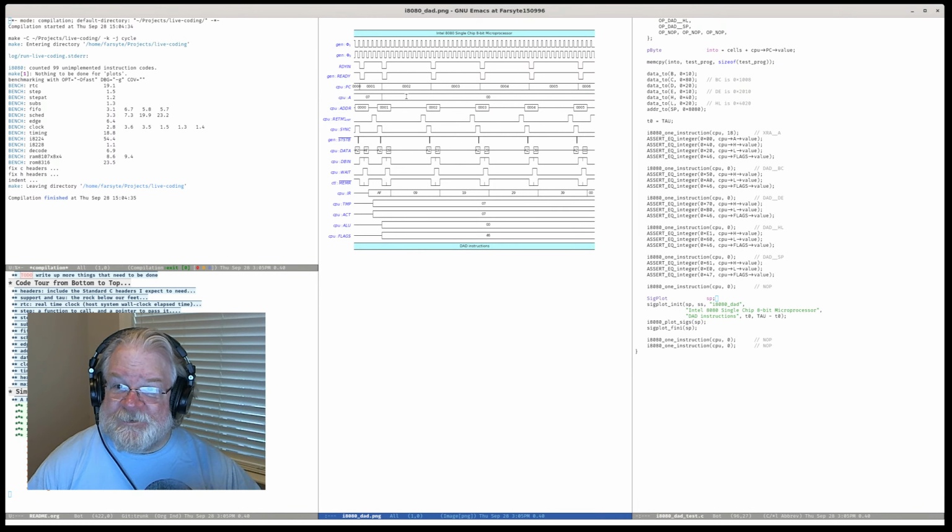SP is marching across. The accumulator gets cleared to 0. Here's our ret M1s. Notice our NOP is very much shorter. These guys are long. These M2 and M3 cycles are non-memory cycles. We're not referencing memory at all. We're not even doing a sync. I'm double checking that.